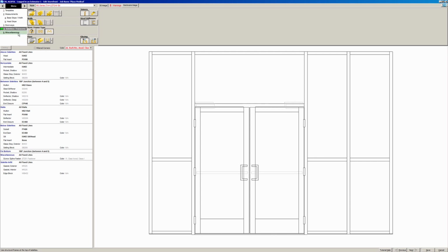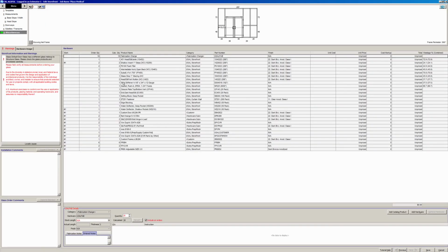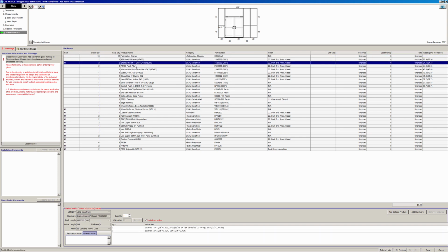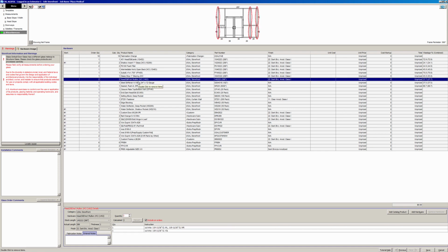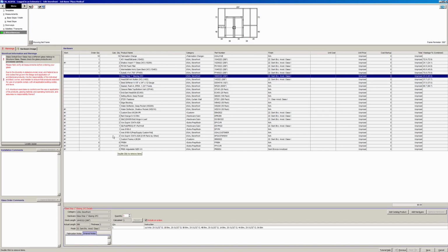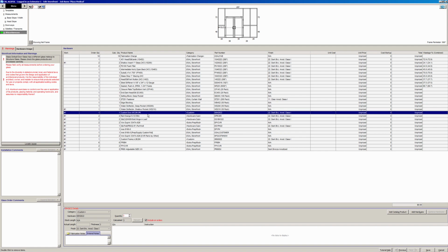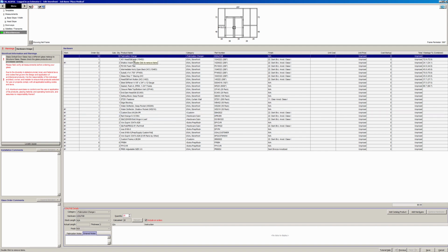After the screen's done here, you can move on to the miscellaneous sheet. This will show you all the component parts needed for the project. The system automatically optimizes all the cuts, all the metals to finish the job. If you feel you need more metal at a certain point, then you can simply highlight that part and change it with the quantity field here, up or down. This also has our door parts. Fabrication charges are there since I selected fabrication by Laurence.